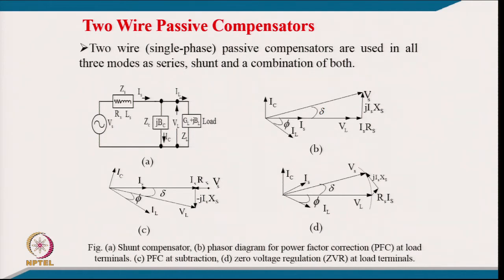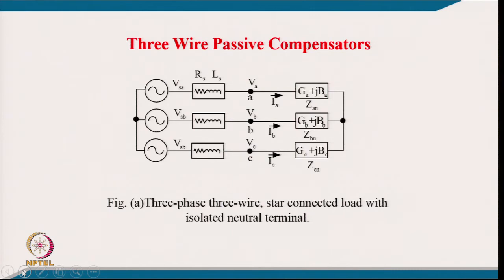Out of the 3 conditions, only one condition can exist, and this certainly gives a design corresponding to the substation, of how much compensator we should put so that the voltage profile can be improved at the substation itself. Normally this condition is preferred by individual industries in their premises, because they are otherwise penalized for poor power factor. So, this avoids the poor power factor penalty, and this gives the real design of how much should be the value of the compensator component.